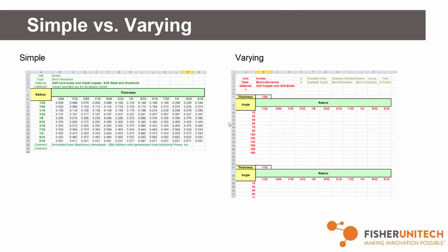The number that goes in that table, what does that represent? Like for 20 degrees, you've got 1/8 of an inch thick. There's a number there. What's that number represent? The numbers under the angle, the numbers in the table that aren't filled out. So that's going to change depending on what your thickness is. Oh, okay. So you're choosing what your thickness is up top, and depending on what that is, that's going to set your bend allowance value. So it's going to take that and bring it over, and then take that number to actually unfold your part and add that bend allowance.